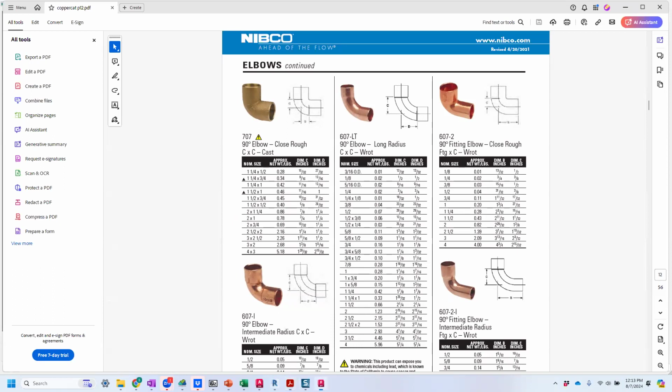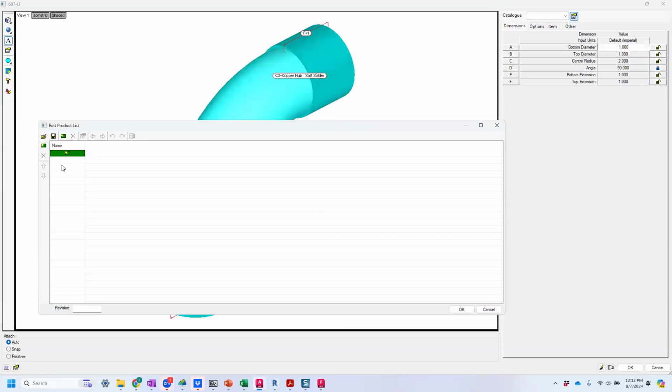All right, so let's go back to CAD, and I'll start my sizes. I'll just do new, I'll do 1 inch, and I'll do 1.5 inch, 1-1/2 inch. And this is going to be my size description. In CAD, if you're building out a report, it's called description. And that's why I actually do the inch mark in there. It indicates to the end user or whoever's consuming this, maybe somebody putting this fitting together in a spool, that that is a size.